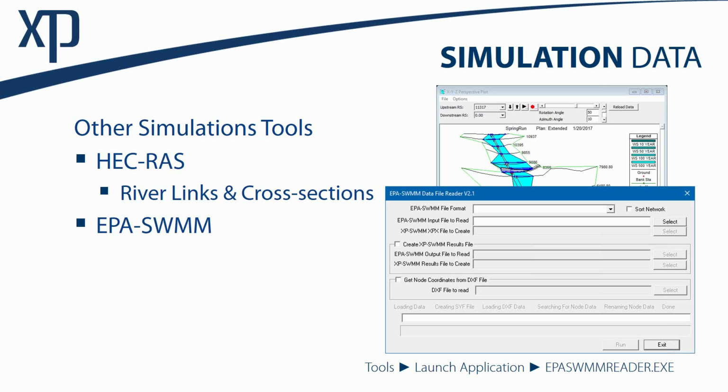We have that ability to not only do surface flooding in the one-dimensional element, but we can actually build that two-dimensional surface flooding stream, overbank it with one-dimensional elements, but two-dimensional surface flooding, inlet surcharging, put it all together so we get a better picture of that broad flood context.